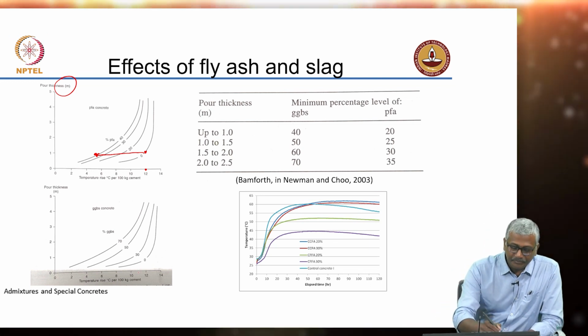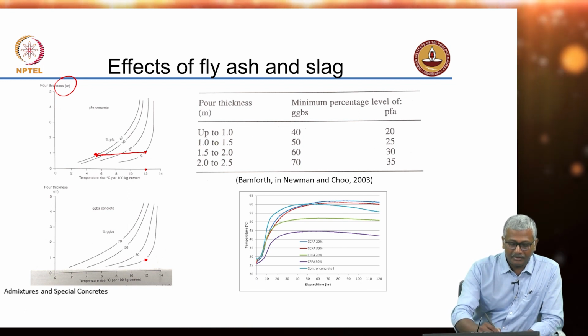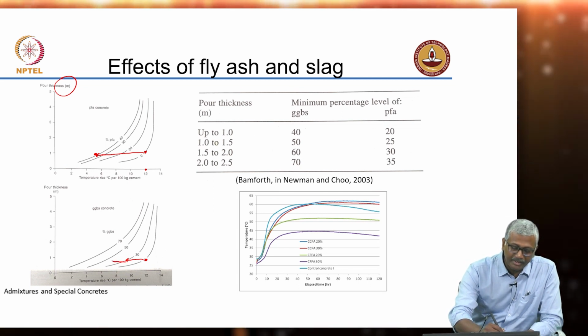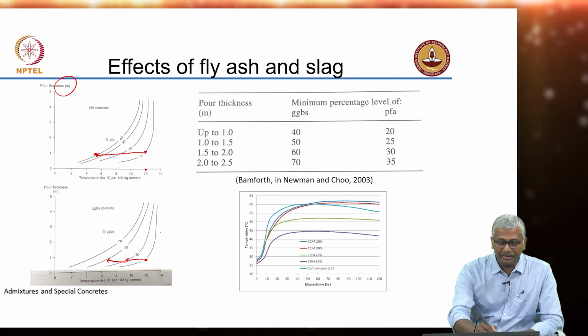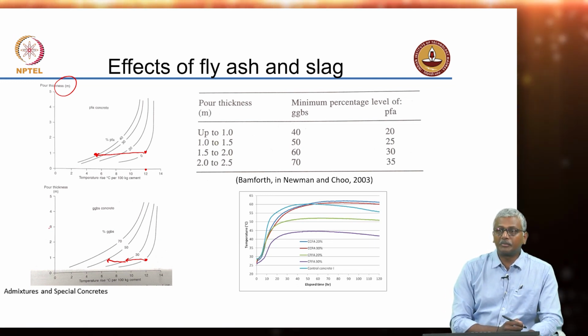With slag, okay, maybe not as much. Let us say here, and when we move to 30%, it is coming down to about 9. At 50 and 70%, possibly I can go down, but that effect will reduce significantly when I increase the size of my concrete member.